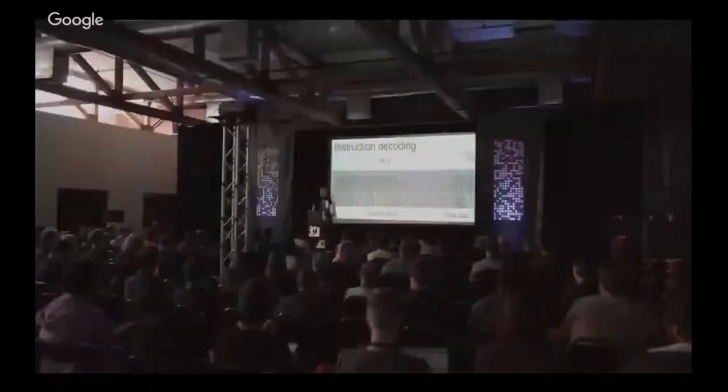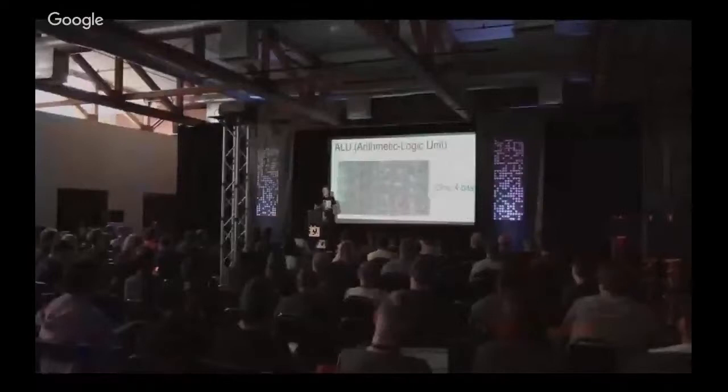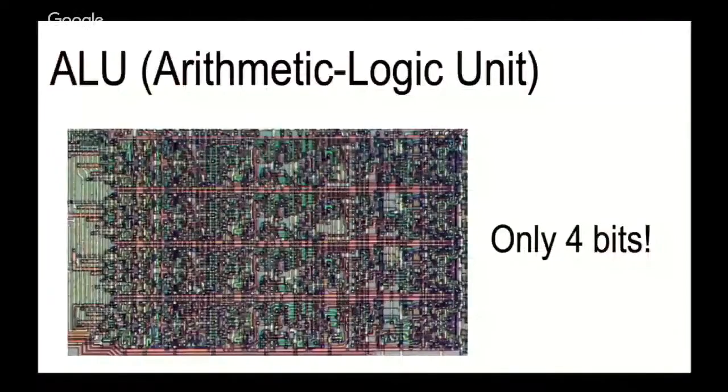The third interesting block is the ALU. This is where things actually happen in the chip, the addition, subtraction, bit operations. Most chips use a bit slice, so for an 8-bit processor, they'll have 8 stacks of circuitry, one handling each bit of the data.